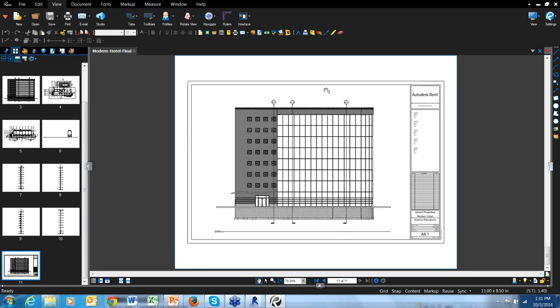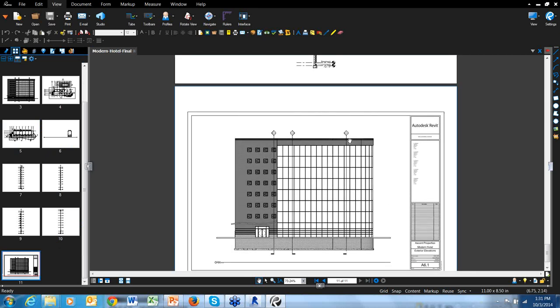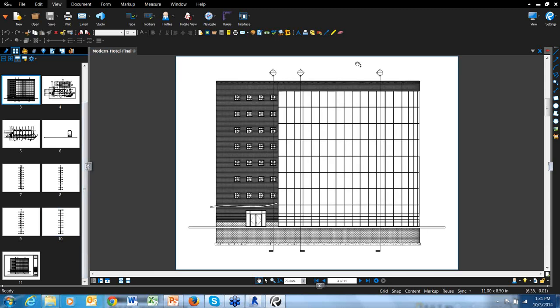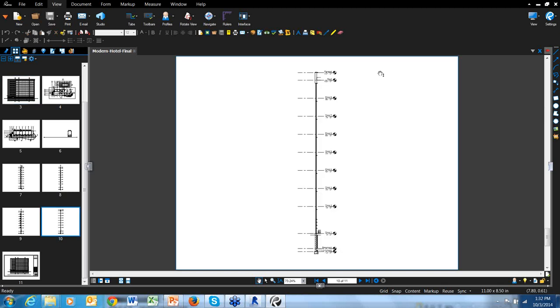And then when you're in the sheet, you can also, when you do the print, select an option to highlight them in blue, so that makes it easier to see actually which links are live in there. And so now, I don't have that one with me, so let's go back here. And so the section view, all I'm going to do is click on my section marker and it switches me to that section.